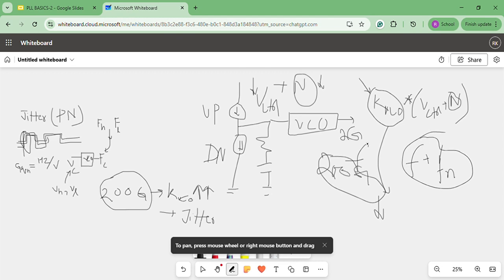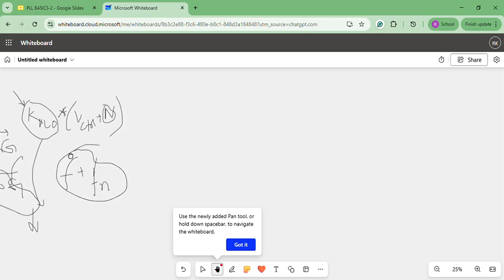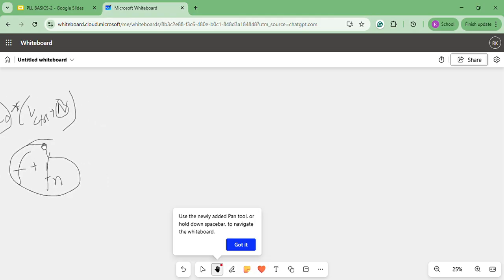We can generate a high frequency, but when we need a 200 gigahertz frequency, we'll simply use a multiplier of 100 to get 200 gigahertz. So 2 gigahertz is the output of our PLL, and we'll multiply by 100 to get 200 gigahertz of frequency. Next we'll take an example with some numeric values to show why we are focusing more on the VCO. As I already told, VCO is one of the most important blocks, so we should take utmost care while designing it.